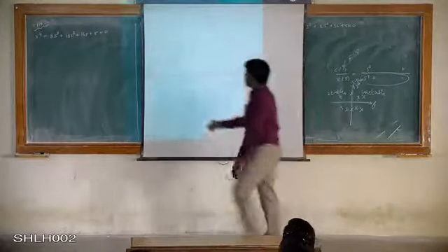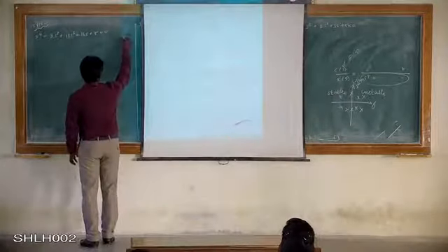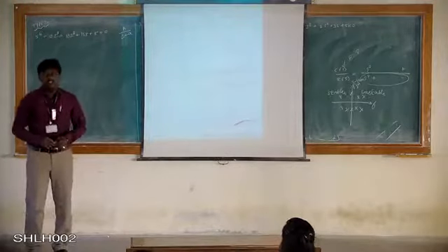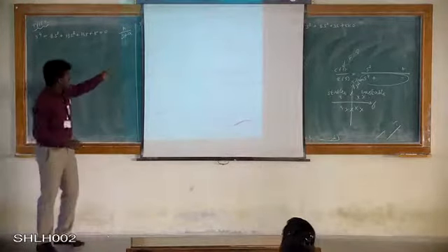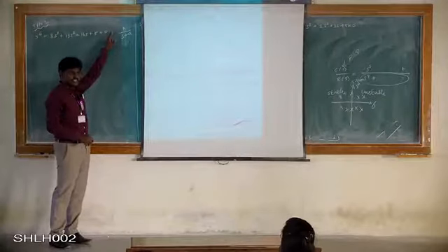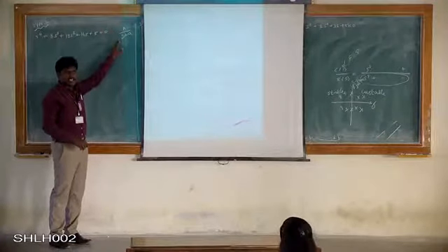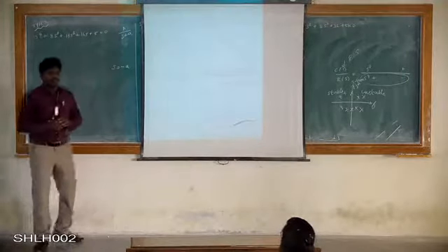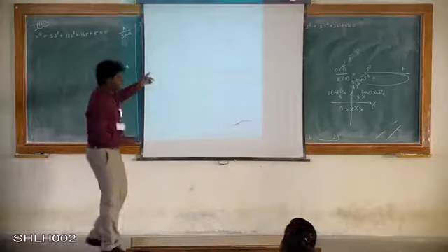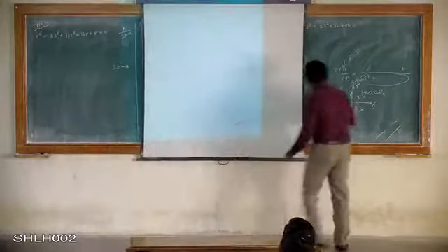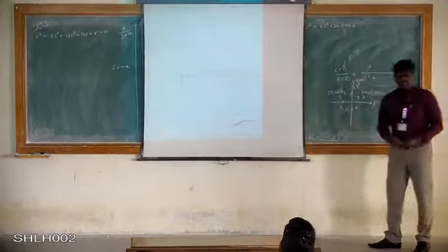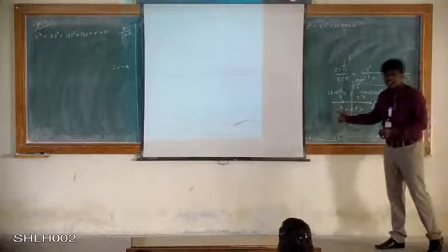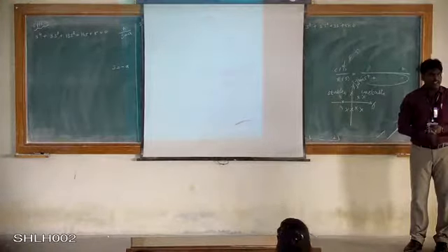Right. So here you have S plus A, an equation like A divided by S plus A. As I said, you have a transfer function with numerator constant value A and denominator S plus A. What are your roots for S? S is equal to minus A. If you are plotting in the S plane, your roots will be lying on the left half of the S plane. If the roots are lying on the left half of the S plane, then the system will be stable, right?